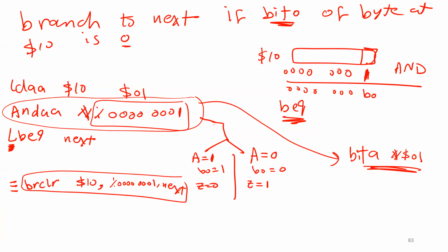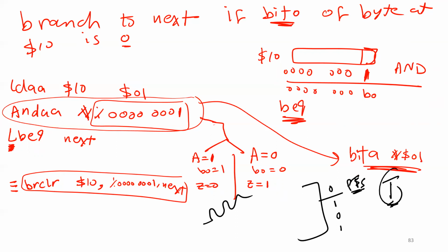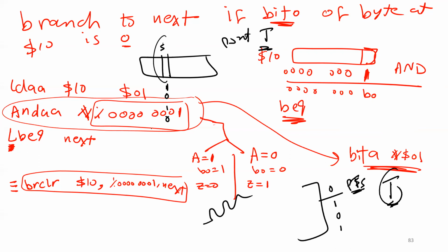One time I was in the lab, and this buzzer is connected to one pin in port T, and in order to make some sound, you have to put 0 here for some time, and then you put 1, 0, 1, 0, 1. You make a square wave, okay? As I'm going to explain in the next chapter. This is pin number 5, on PT5, port T pin number 5. So the way you have to do it is, you have a byte, which is port T, and I'm only interested in bit number 5. In bit number 5 here, I have to put 1, 0 in order to make this sound. Is that okay?